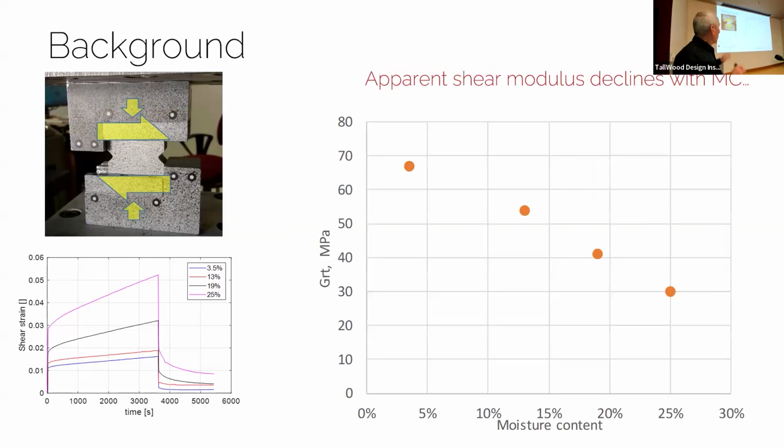And if you think of what would be the equivalent shear modulus after the period of time, it just declines rapidly. And this is very far from the published value, about 500, based on this Bodig and Herman-Patton publication. The shear modulus in the transverse direction will be about 500 megapascals. It's like 50 megapascals. I don't think we are incorporating this in our design procedures, right?